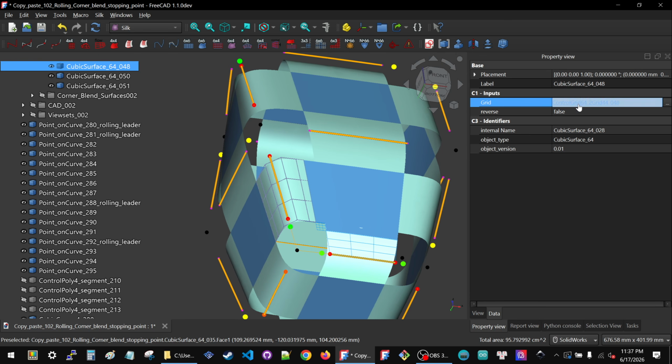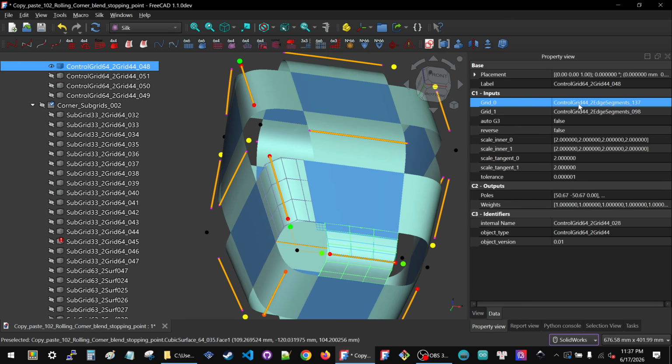This guy has a control grid. I show it. This control grid is currently reaching all the way back up to this point here, which corresponds to the red point. I want it to move down, so it corresponds to the green point. I will do that by swapping in this new smaller grid. Which one of the two is it? Well, if I remember correctly, because my span curves run from bottom to top, I should have done this one first and then this one. That means that once again, it should be the second piece.